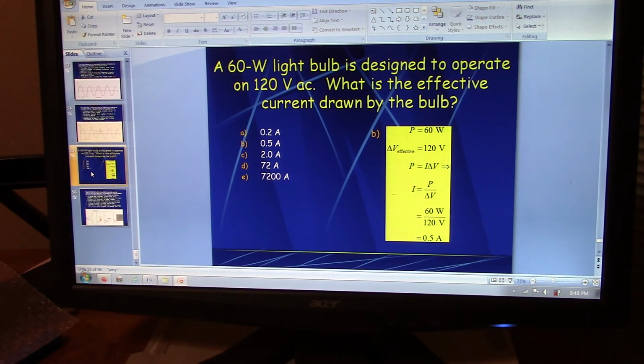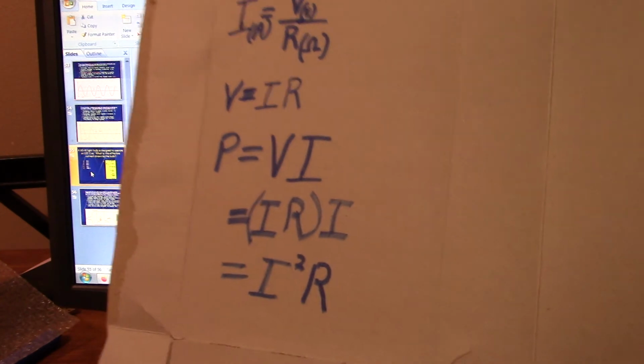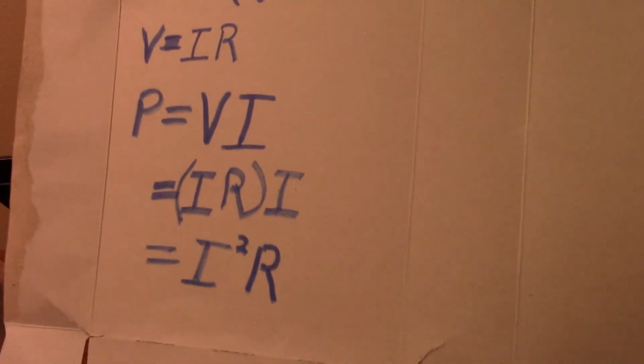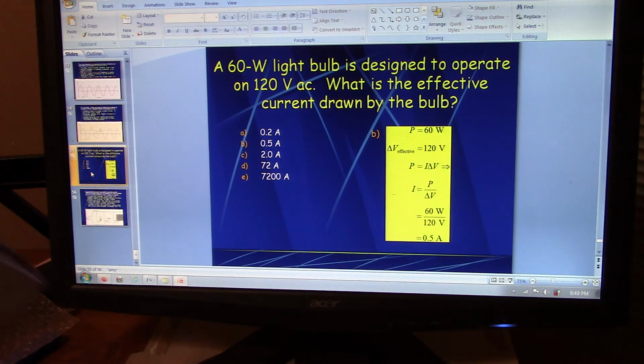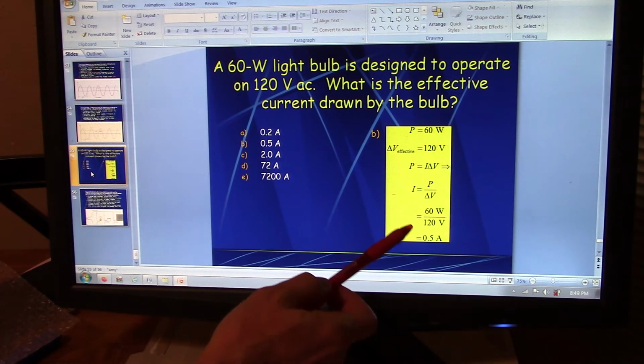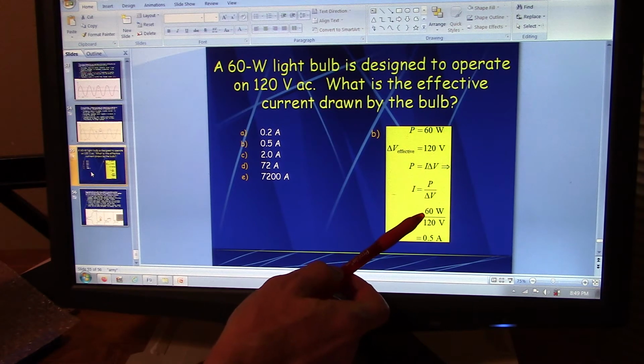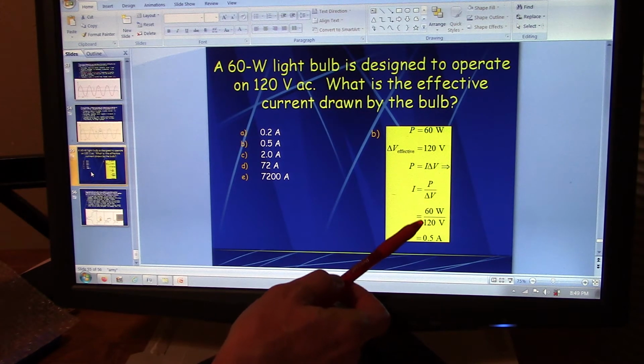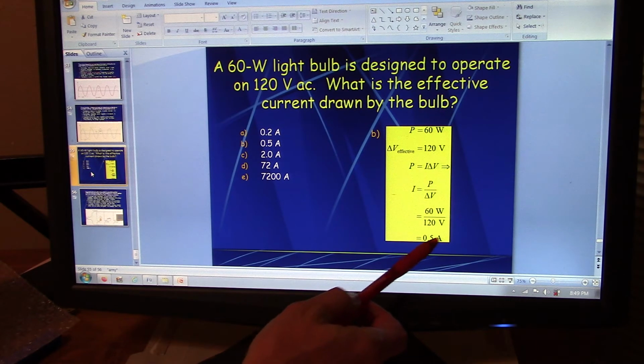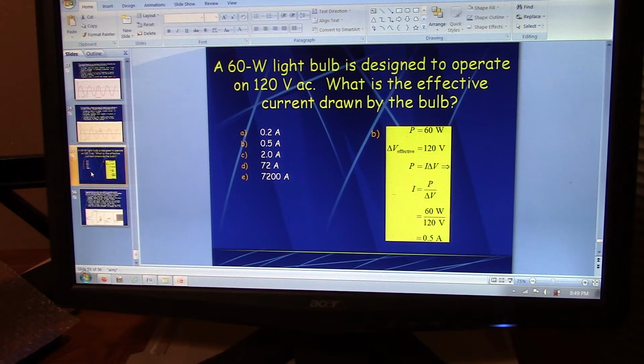Here's what I wrote down. Power is equal to voltage times your current. So your current is just your 60 watts divided by the 120 volts going into your house. That light bulb is using half an amp, 0.5 amp. Ta-da! Isn't that cool? Physics. No longer are light bulbs a mystery. How does the light bulb work? You folks know how. There are people that are big shots in companies and think they're all that, and you know more than they do. And you do, for real.